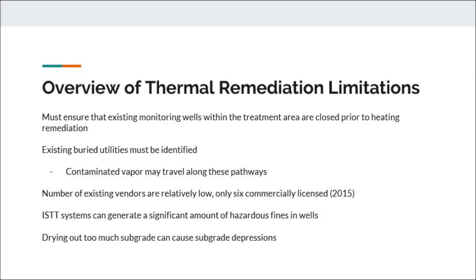Another limitation with this treatment method is that the number of existing vendors is limited, and furthermore, in situ thermal treatment technologies are growing but are subject to patent protections and licensing requirements. As of 2015, there are actually only 6 commercially licensed vendors to complete these projects. Another limitation of thermal remediation as a whole is that these systems can generate a significant amount of hazardous fines in the wells. This can be avoided though through proper well management and using things like well screens and sandpacking.